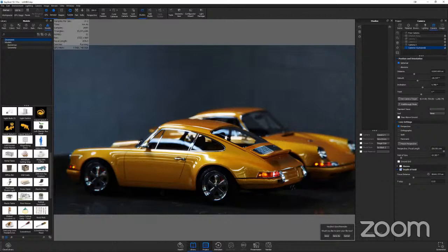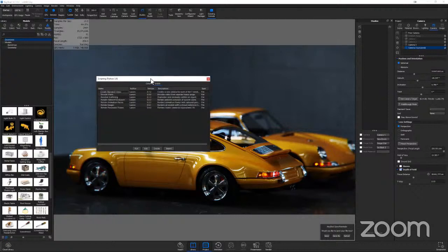If you go up to the top next to the light manager and right mouse click there, you should be able to bring up, on the top ribbon all the way to the right... Yeah, keep going, where it's blank. And then right mouse click, and then bring up scripting console. It's kind of hidden, and then you click on that. For folks who are curious about Python scripting, there's some example scripts included in that console, so creating standard views, different things.